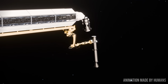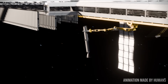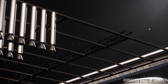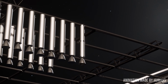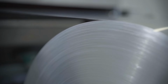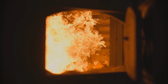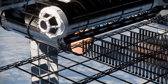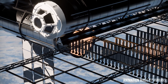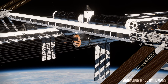And we should care about simplicity specifically for disassembly, because once these rocket pods reach the orbital depot and offload their cargo, we'll be left with what is essentially a spent casing, and we'll want to recycle these at the orbital depot because these casings are themselves refined, usable mass, likely aluminum or iron. So we'll probably need meltdown hardware at the station, and this has another implication too, which is that whatever the casing or rocket pod body is made of will be the thing we ship the most of. So if it is aluminum, we're going to be sending tons and tons of aluminum just to deliver other things.